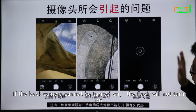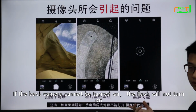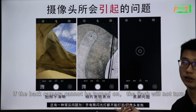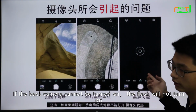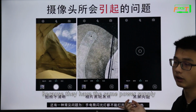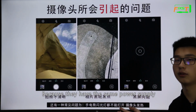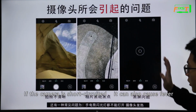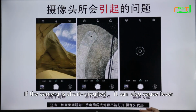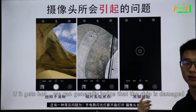If the back camera cannot be turned on, the flash will not turn on, because they have the same power supply. If the camera is short-circuited, it can also get hot. If it gets hot, we can generally judge that the chip is damaged.